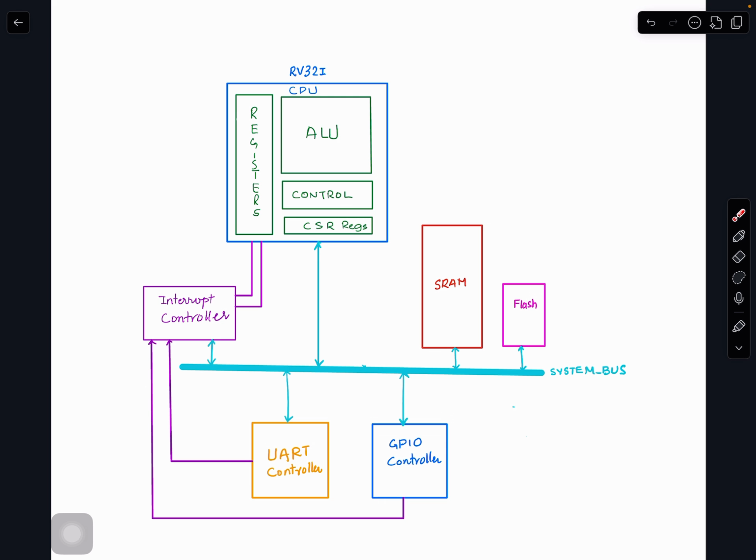So those addresses are part of those 32 bits. Here is something new you're learning. Those 32 bits that we thought were all for SRAM are actually not all for SRAM. It's still an address. So the CPU accesses as if it has one continuous line of addresses. But actually we have assigned some addresses for this, some for this, some for this, and some for this. This is called address mapping, or the memory space, where certain parts are mapped to different things.